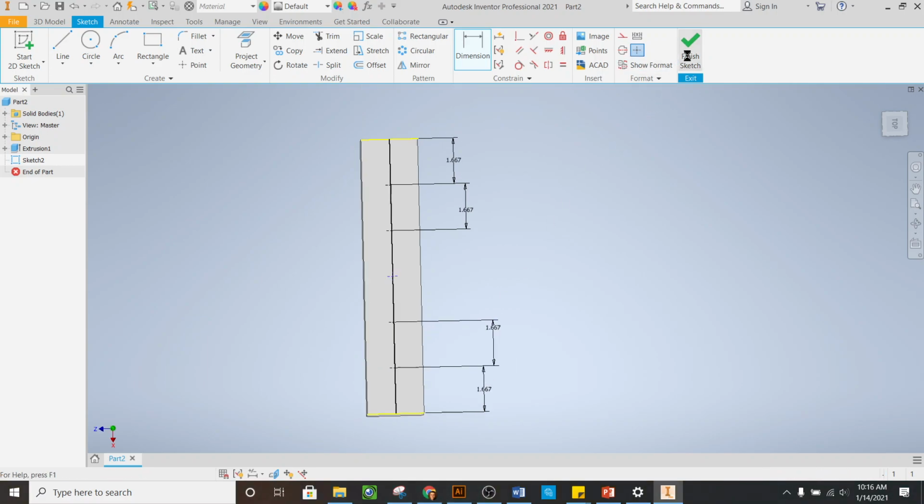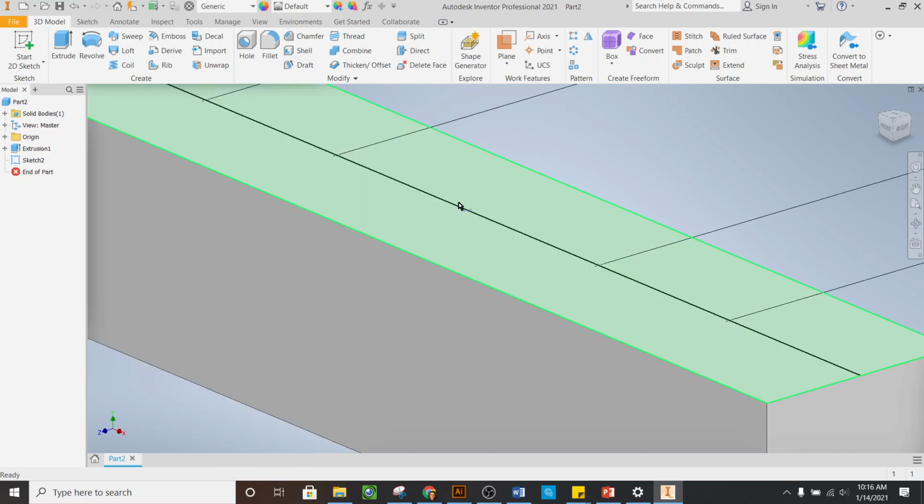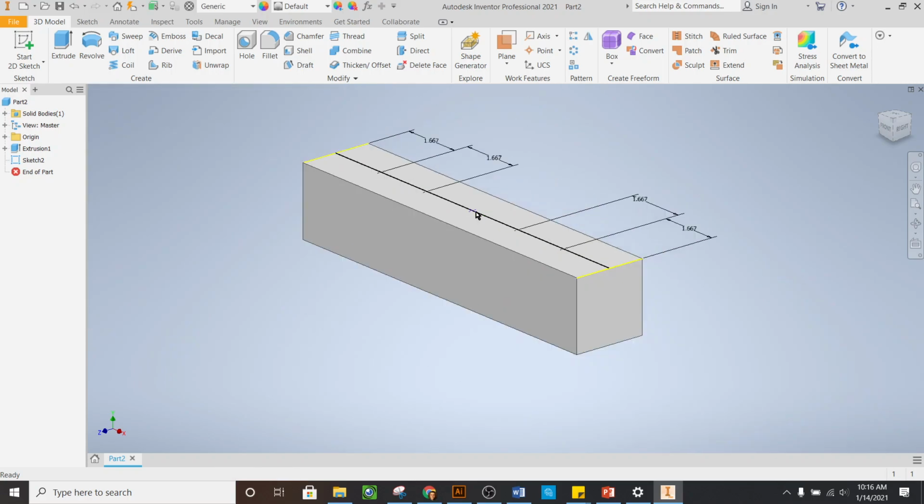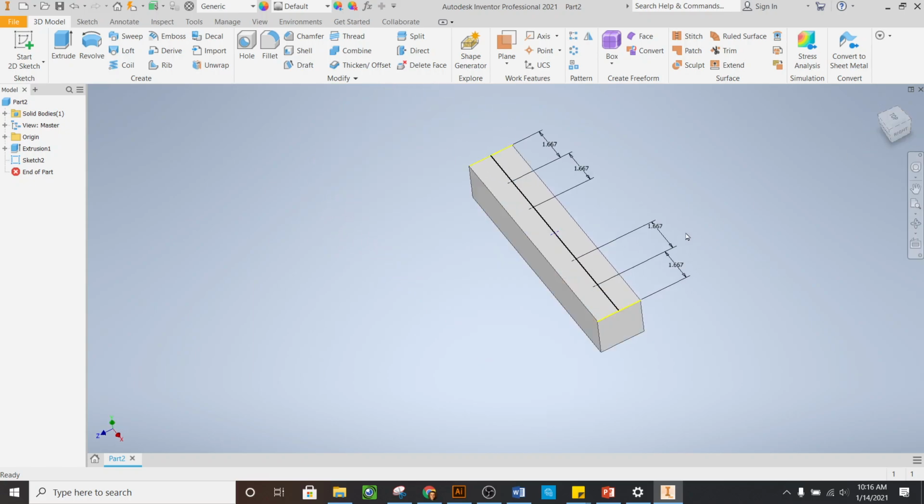Okay, finish sketch, and you should have these 3 dots. For the one in the middle, I didn't put a dimension because it should have automatically snapped to the midpoint, which would be 5 inches, so we don't have to worry about it. Check it over and make sure you've got those dots. Once you've got all those dots in place, we will start using the hole tool.